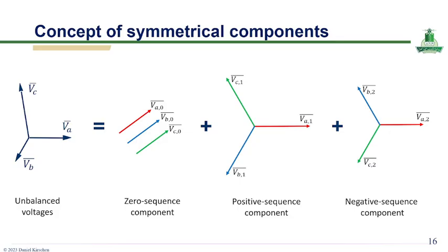So this slide is showing the fundamental idea of symmetrical components by showing how an unbalanced three-phase voltage system can be decomposed into three balanced sets. So you can see that the unbalanced voltages can be the combination of the zero sequence component, positive sequence, and negative sequence component.